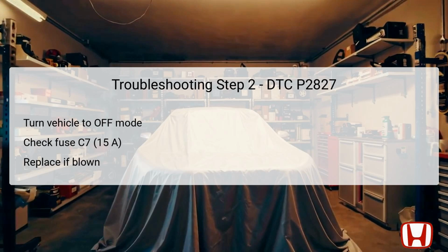However, if the fuse is blown, replace it and confirm whether the issue persists. If the new fuse blows again, that indicates a short to ground in the circuit that will require careful inspection and repair. Addressing fuse issues can often resolve DTCs effectively without requiring further invasive diagnostics.